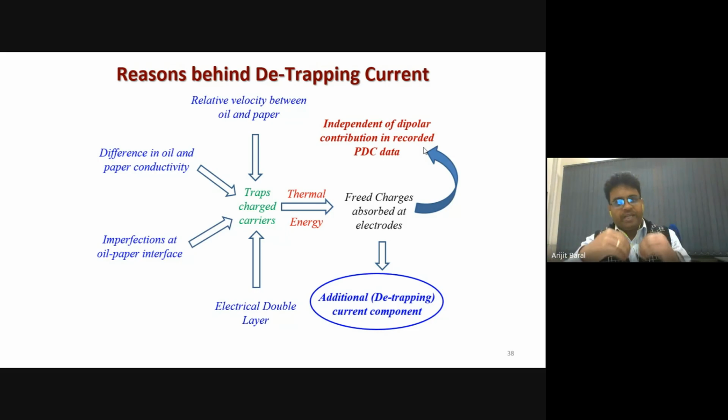Now, if the speed of the oil is sufficient, what will happen? The positive part of this aligned dipole will be stripped away by the moving oil and ultimately taken with the flow. Because this oil is in contact with the grounded tank, the positive part of this separated dipole will be grounded and neutralized at the tank, but the negative part will remain in the solid insulation.